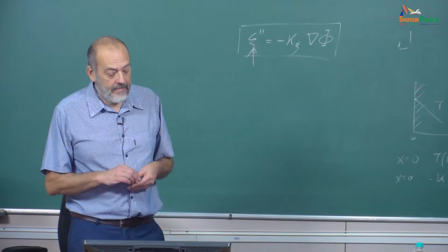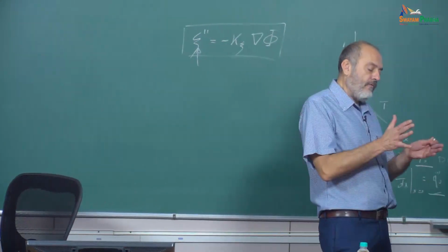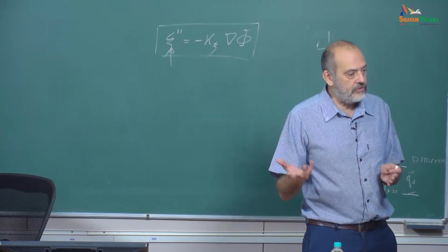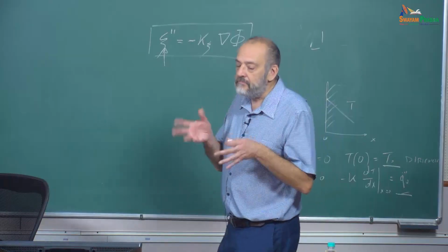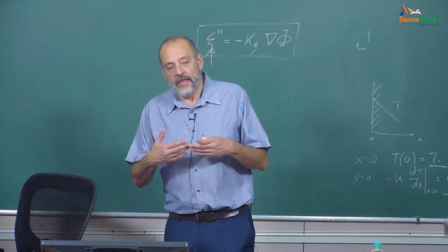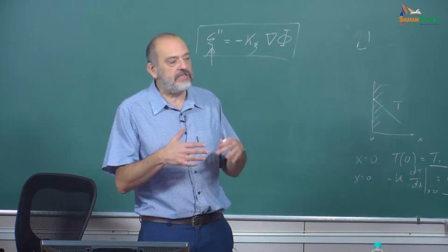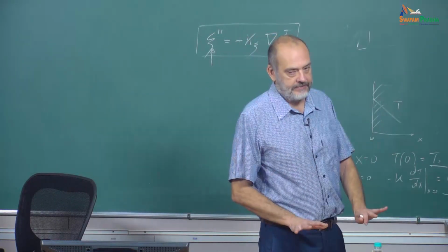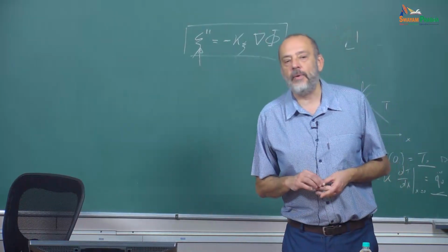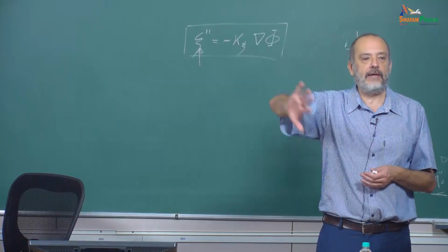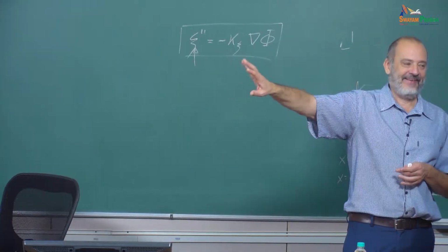Why is the Reynolds number so important? Because there are criteria saying that above a given Reynolds number, the inertia is dominating. So the viscosity is somehow less important. So the viscosity is not able to dissipate the energy at the various scales. We are entering now in the domain of turbulent fluid mechanics, which is again another course. So I cannot do it, okay?